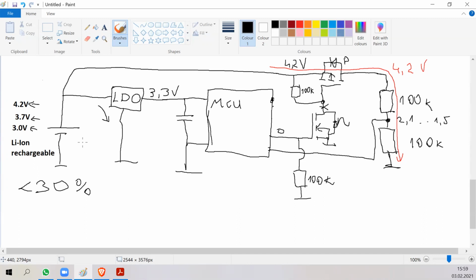And it turned out that the previous engineers had just put the N-channel MOSFET at the bottom of this resistor divider. So there was constantly, all the time, leakage from the battery through the top resistor into the microcontroller, through the ESD protection diodes into the power supply.